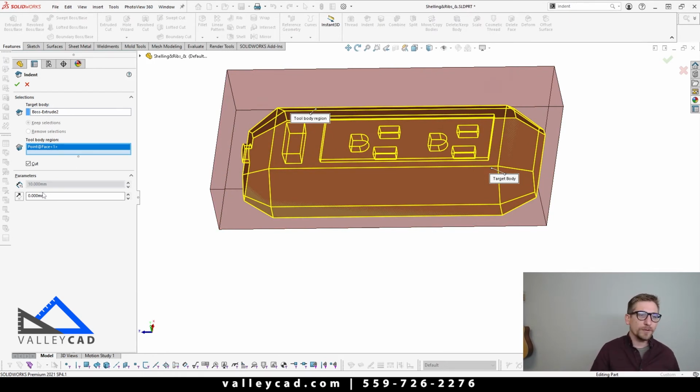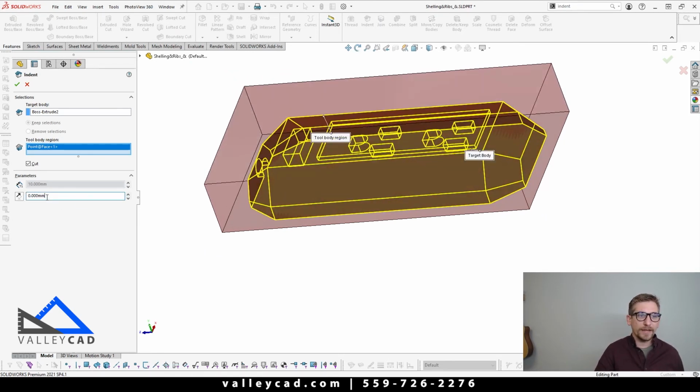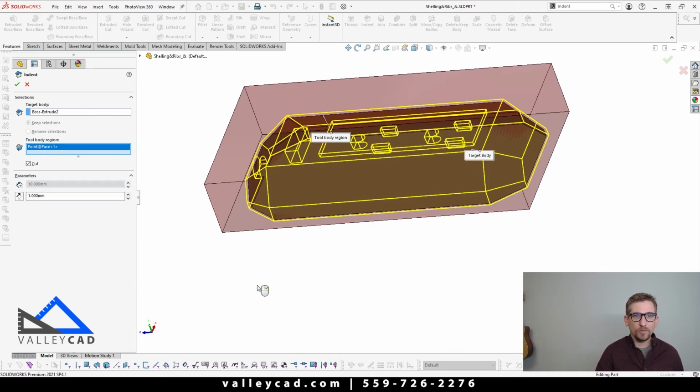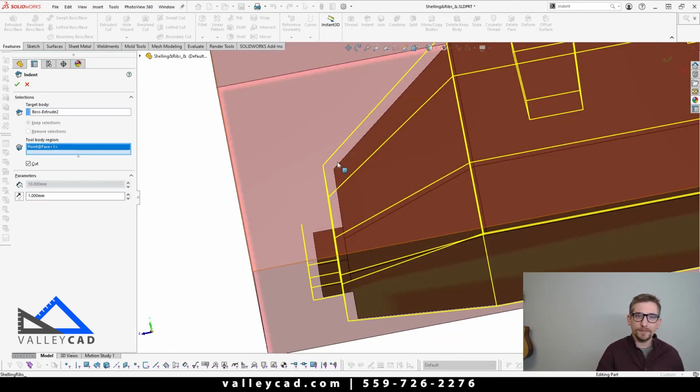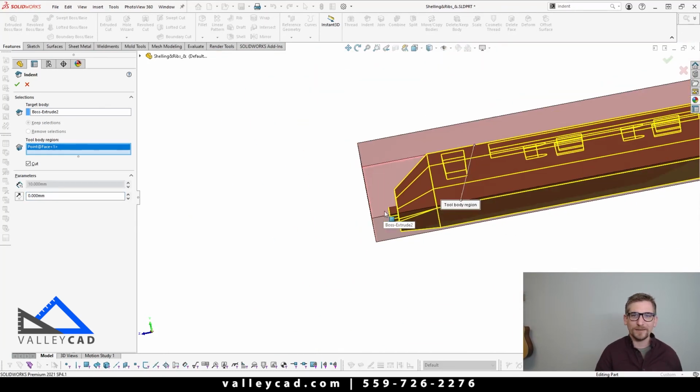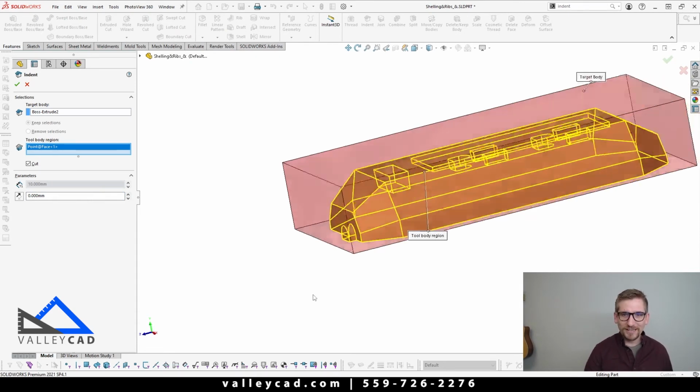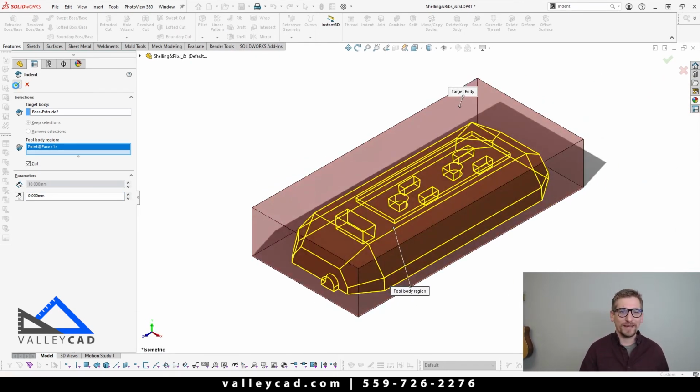And also, if you are dealing with an injection molding part, as something cools, it will actually shrink a little bit. And so you can actually create an offset here if you wanted to. So if we say, hey, yeah, let's make it 1 millimeter, you'll notice how it offset 1 millimeter from my original model. In this scenario, I'm just going to say 0 at this time. We'll make it an exact fit, right? All right, so we'll come in here and we'll simply say okay to that.